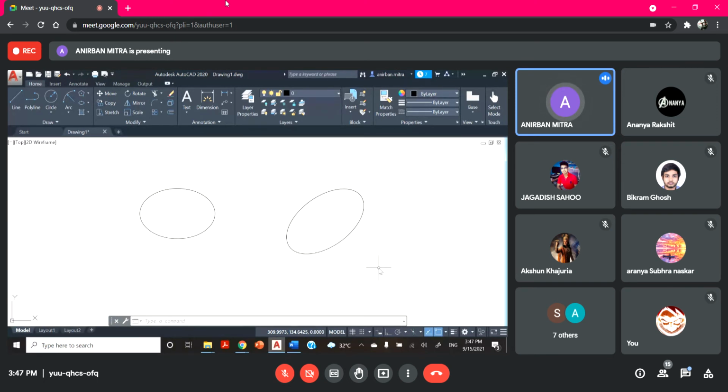So when we go for a relative coordinate system, you have to indicate to the software that you are actually going to provide a relative value. That is designated by the @ symbol, which means that if I draw a line like this, this is the first point. The next point, if I put @ now, it means that the reference point now becomes the first point, the point that I have already selected, already clicked. Otherwise, if you are going for absolute coordinate system,